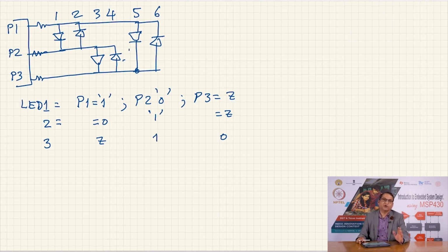So, if you go much more than that, let us say we turn on and off each LED at 100 hertz, and since these are 6 LEDs, if I have a mechanism to turn on and off things from a microcontroller point of view at 600 times a second, then each LED can be turned on and off 100 times a second, it will give me a comfortable display.